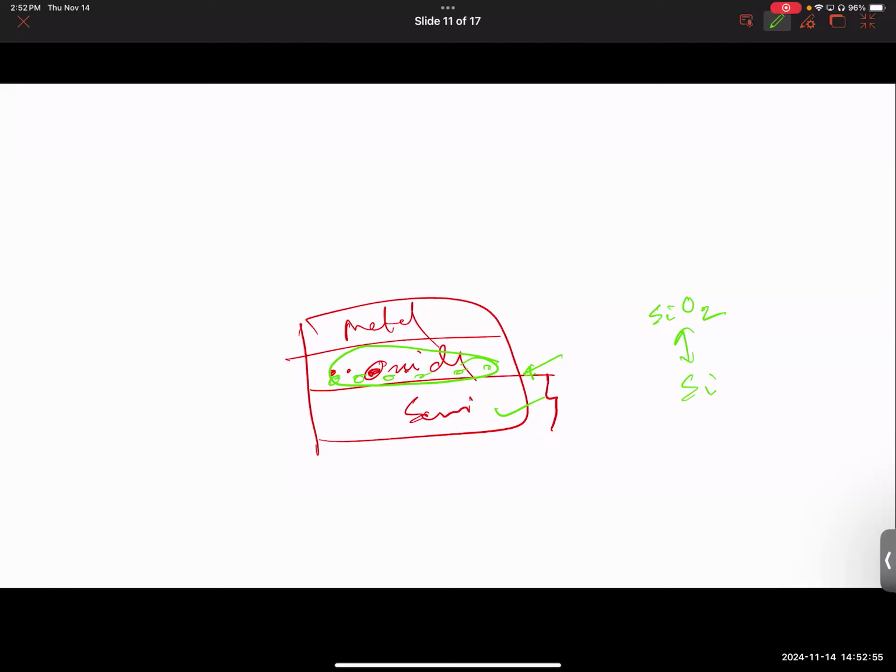The layer where they match, there will always be mismatch. They will look different. You could easily figure out that there is some asymmetry there. So when silicon oxide and silicon meet at the interface, there will be broken bonds, and those broken bonds typically lead to positive charges. It's very exceptional to get any kind of negative fixed charges in oxide.